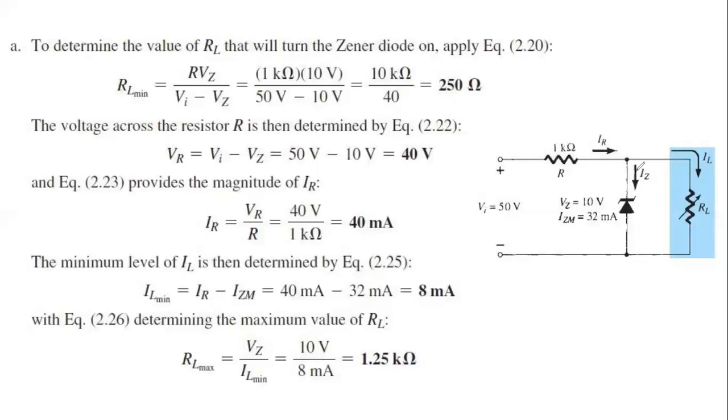My students, the minimum current we already found out is 8 milliampere. Why is the maximum current 40? Because the input current is 40 milliampere. We all know that this is a two-way device. So when will it be the maximum? When the Zener diode is reverse biased, and at that time there will be no current flow through it. So the total 40 milliampere current will flow through this resistance. So that's why it is told that the maximum current that is possible in the resistance is 40.